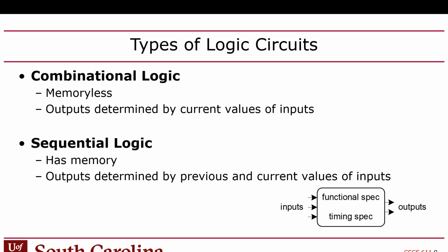So you change any of the inputs, and the output may be updated to reflect that change. And then there's sequential logic that involves memory. So in a sequential logic circuit, the outputs are a function not only of the inputs, but of the history of inputs that were given to the circuit, because it has a memory. The memory can be RAM, or it can be flip-flops or latches. And hopefully you learned a little bit about that in 211.